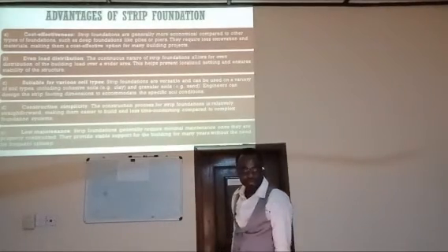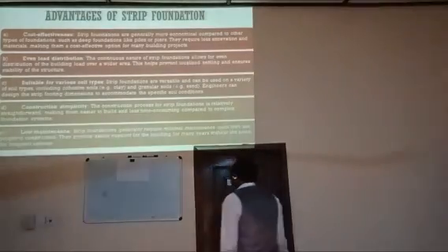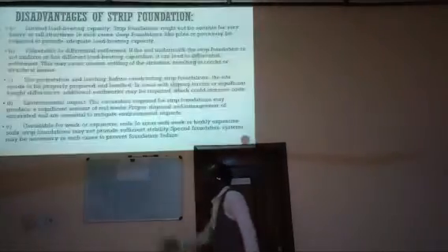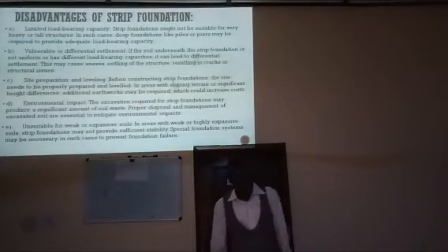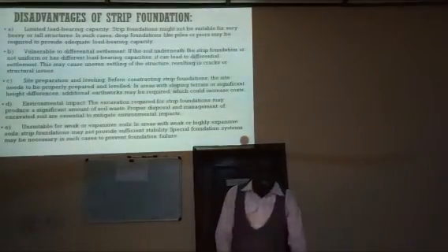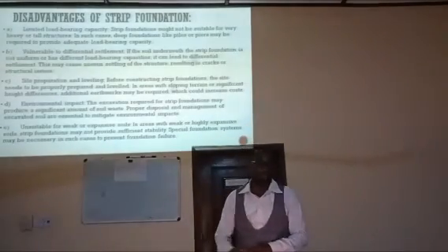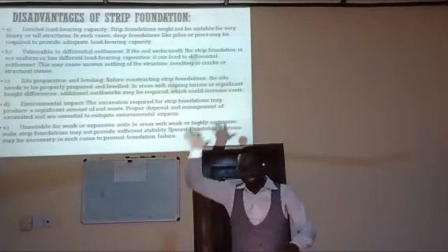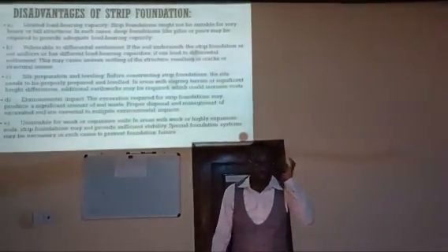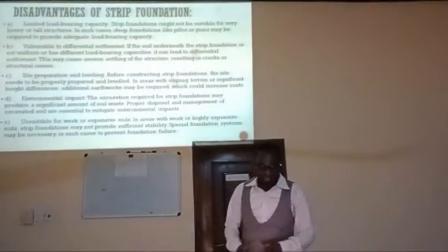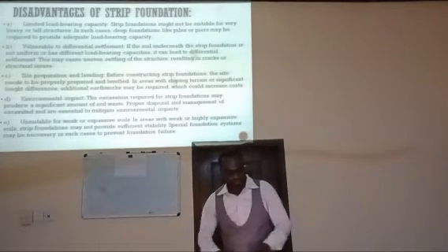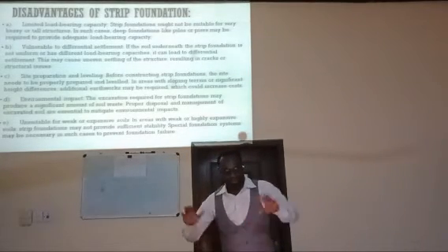Yes, it is. Because when you have used strips, remember that if you did not capture it well and use its sloping place, and you did not use the steps well and arrange them in such a way that the steps should be able to take care of every part, you discover that cracks will start developing, and from that crack, some differential settlement will start happening.